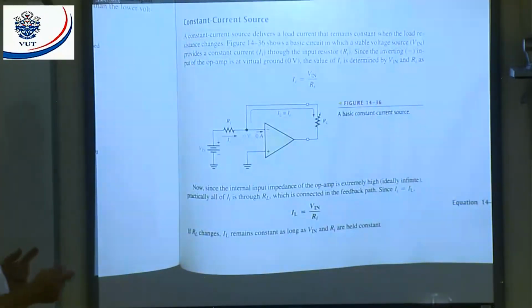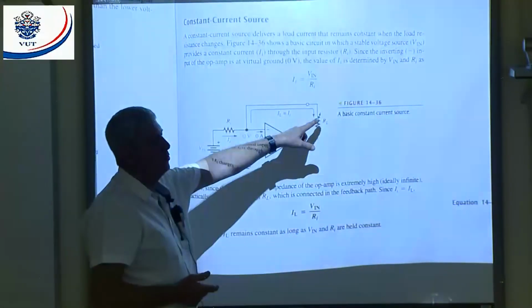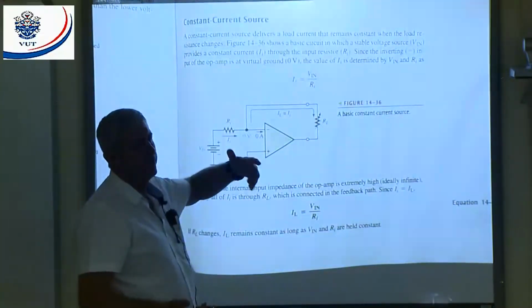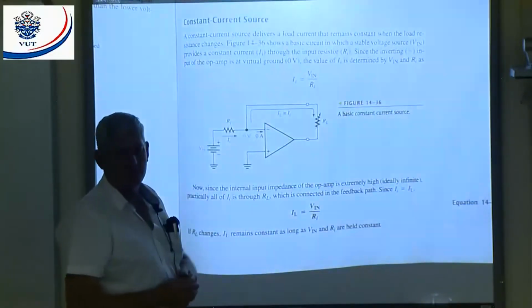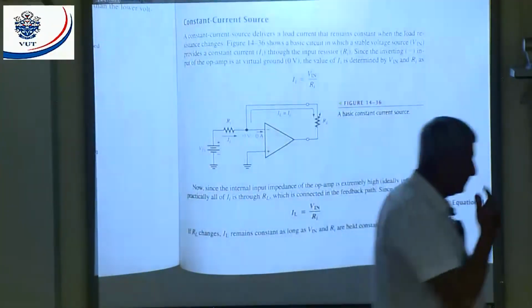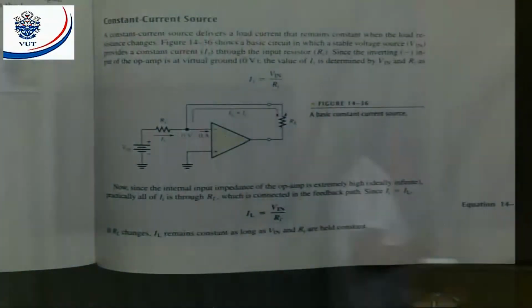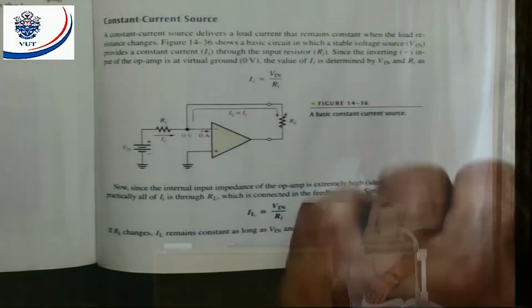But remember, you can't make that too high. If you make it too high, you will reach a certain point where the op-amp will saturate, and it won't be able to keep the current constant. Any questions?